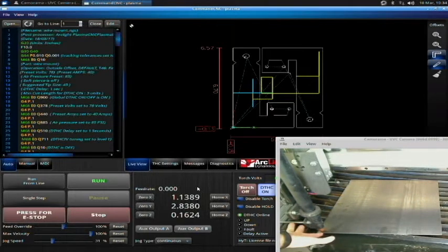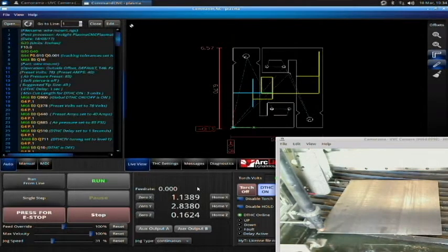So I don't want to start right on the edge. Inset a little bit from the edge in this way, inset a little bit from the edge that way. Okay. Now depending on how comfortable you are will depend on how much room you give yourself, but I recommend initially 1/4 inch. So give yourself some extra room, because you do not want to run off the edge of the plate and lose arc.